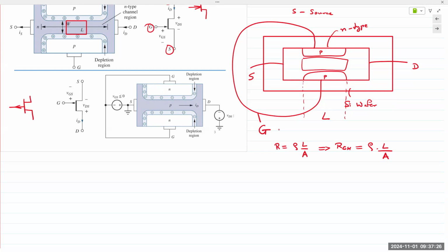So we have a semiconductor, right? The semiconductor, you're going to implant either N-type or P-type material. When you implant it, it goes into the surface. It does not go too deep, it's shallow. So for a 500 micron wafer, it's probably just a few microns from the top. When it goes in there, the implant is buried inside. And so there is a shallow layer of the channel that is a few microns deep. So the depth of the implant is basically the thickness, and that gives us the cross-sectional area.